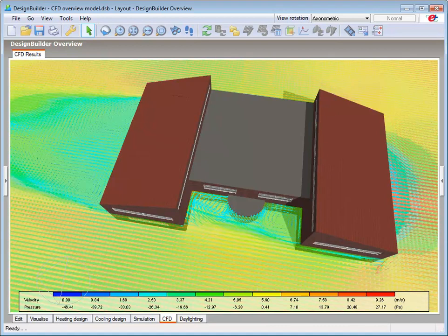However, internal analysis boundary conditions are generally more involved and require the addition of boundaries such as zone surface temperatures, airflow rates through exterior windows and vents, supply air diffusers, extract grills, temperature and heat flux patches, and often also the incorporation of model assemblies representing occupants, radiators, fan coil units, heat generating equipment such as computers and servers, etc. These will be discussed in more detail later.